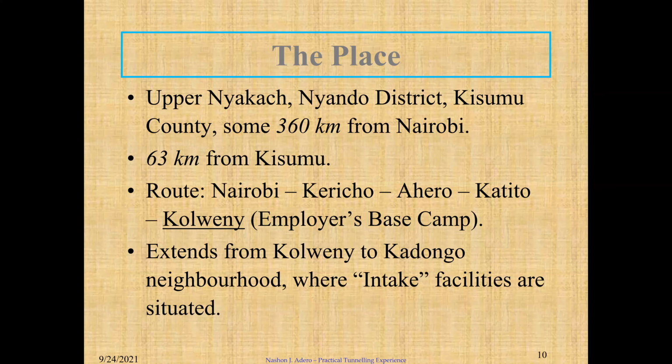Again, engineering surveying is critical to aligning these intake facilities, the intake weir, so that you can have it located in the correct place, X, Y, and also vertically the Z. And you must have the gates well set out to be within the right location according to the design, so that water can enter the tunnel at the correctly designed location, to control the water velocity as it enters the tunnel. So those gates should also be controlled.